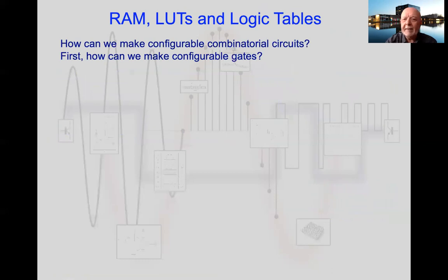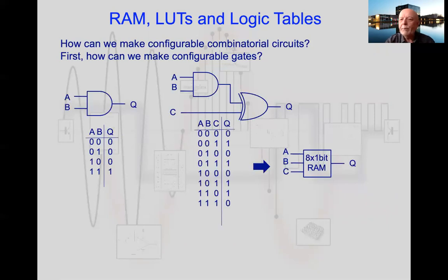So the first thing, let's think about configuring combinational circuits. How are we going to come up with a system where we can configure combinational circuits? Of course, what we're not talking about is discrete logic circuits where we change the wires around. Not very autonomous. But we already know about this. If we think of our FPGA systems, they're not actually implementing the logic in gates. It's actually done within a piece of RAM, a small piece of memory.